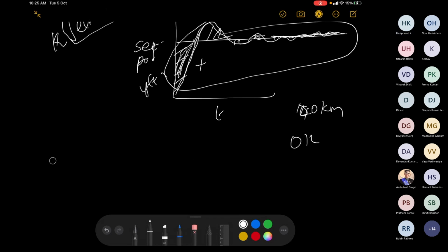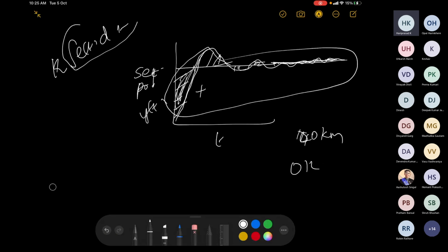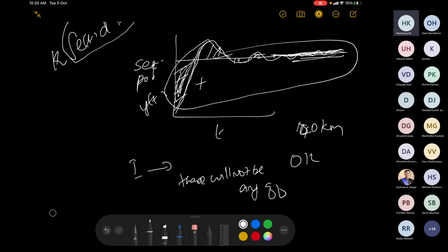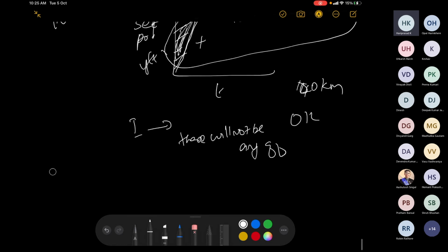Okay. So there would always be an integral action. As a result, when you apply integral action, you will see that there won't be any offset. Offset is the variation from the set point, right? Your controller action cannot be off. Your integral action keeps on supplying the control action, even if the error is close to zero. So there won't be any offset, but eventually this would manifest in terms of oscillation.